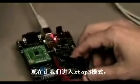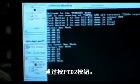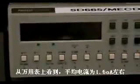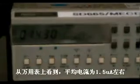And I'll do that by hitting the button here, I believe it's PTD2. That will take me into stop 3. You can see that on the terminal. I'm still going to wake up and update my count and the display every 5 seconds. And you can see that the average current here is about 1.5 microamps, or 1.4, a little less.